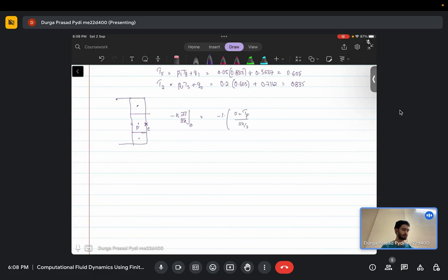So this is very similar to your 1D problem. The only difference is if you are calculating on the east face, you should correspondingly take that particular face. So the flux on any face is given by this. Now if you want the value of the flux, you should just take the dot product with the corresponding normal vector. On the east face, your normal vector is pointing along i cap, so this doesn't change the sign. On the west face, you will get a minus sign, since the normal vector will be pointing along the minus x cap direction.